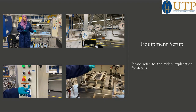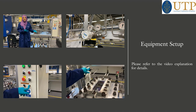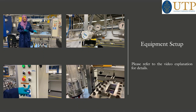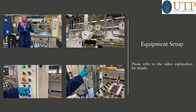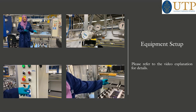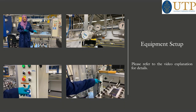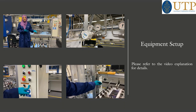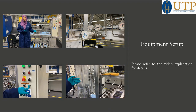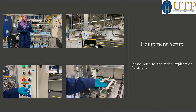Then there is one valve connected with our Micromodel. Whenever you open this one, if I open it, you can see some water goes through this line and back to this container. This one is for maintaining the confining pressure. Then there is V5. If you turn on V5, then this motor will collect water from this container and supply the water inside this system.